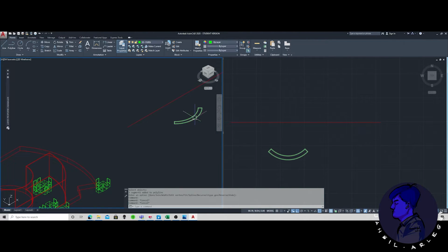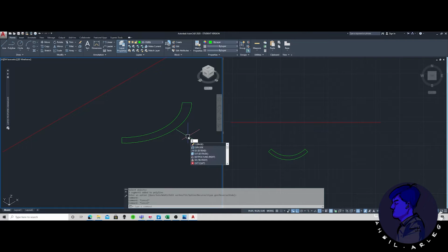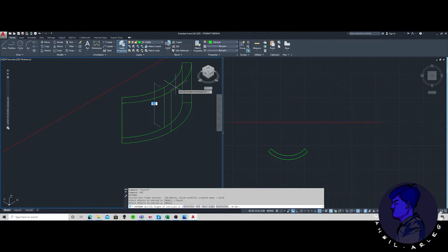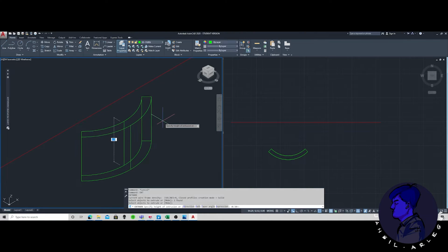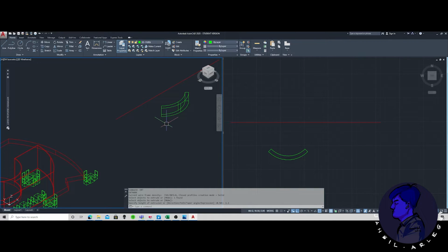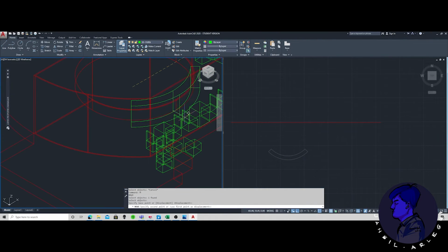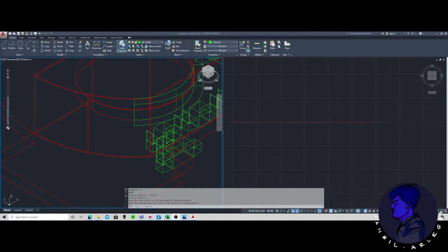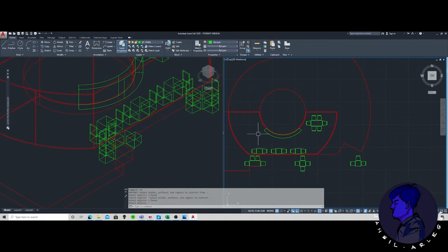A sort of high table. What I need to do here is PX. Extrude this by the height, and so the surface of this is going to be something like 1 meter, 1.2. So I'm going to place this over, move M, center, base, and then place it over the center there. So we can check this on the floor plan. Placed in a few.